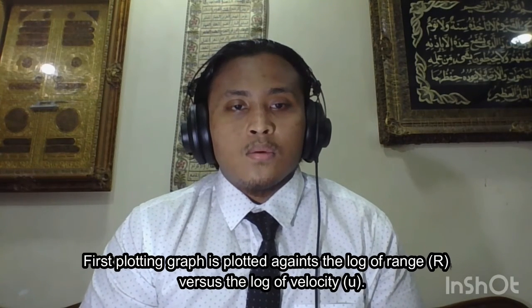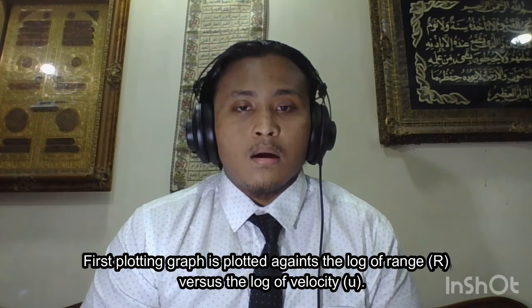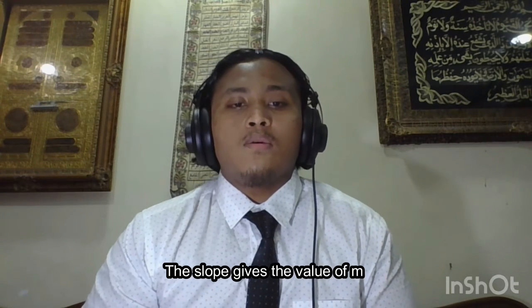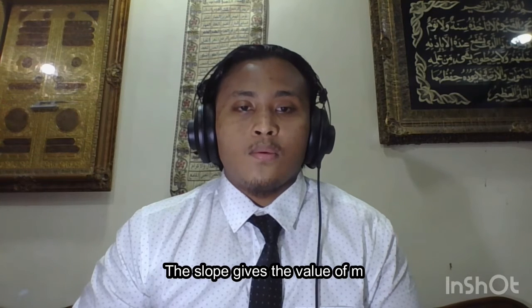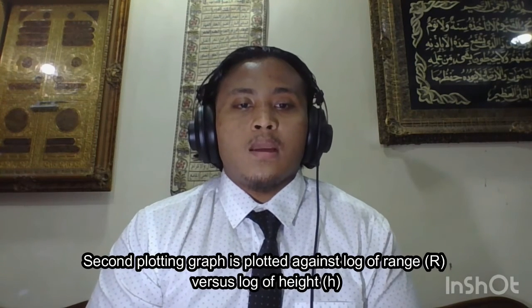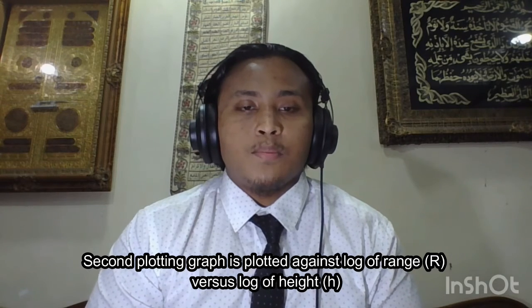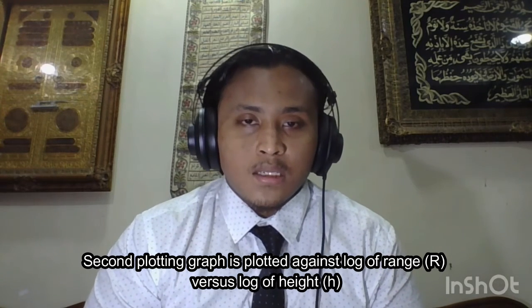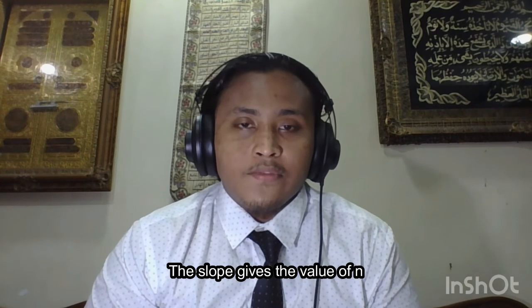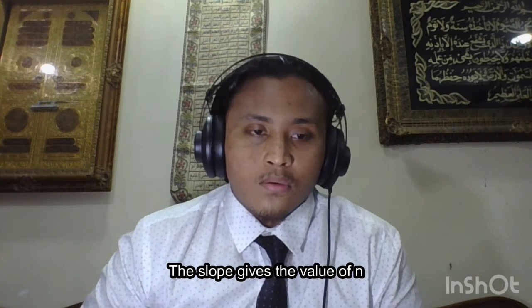First, a graph is plotted of the log of range R versus the log of velocity U. After that, the slope will give the value of M, like the following picture. Second, a graph is plotted of the log of range versus the log of height, labeled as H, and the slope obtained gives the value of N, as follows.